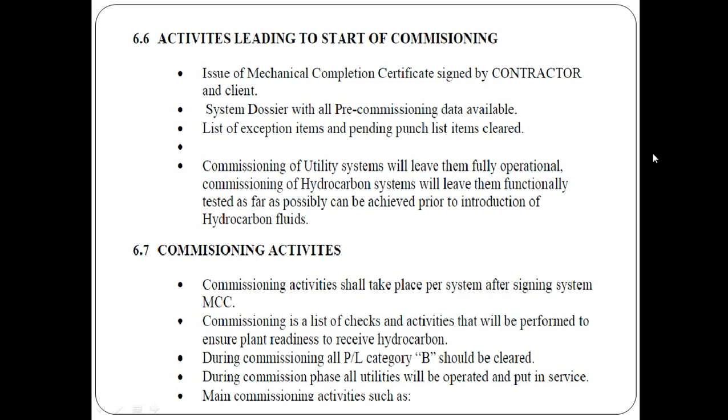This slide indicates the activities leading to the start of commissioning: issue the MCC, system dossiers with all pre-commissioning data available, list of exception items, commissioning of utility systems, and hydrocarbon.